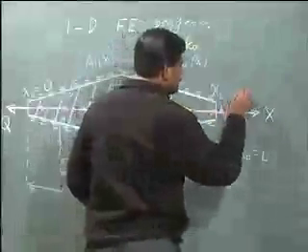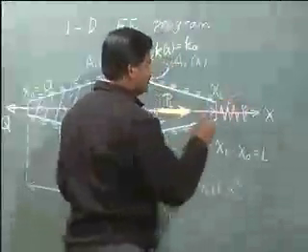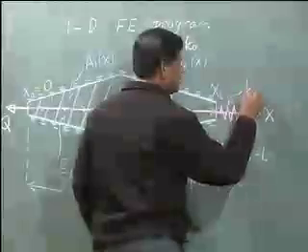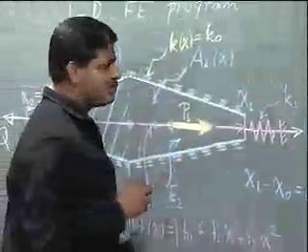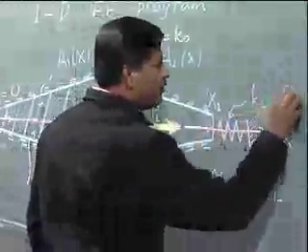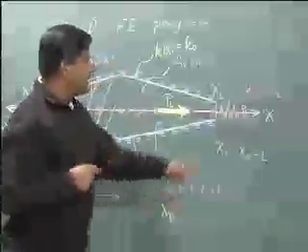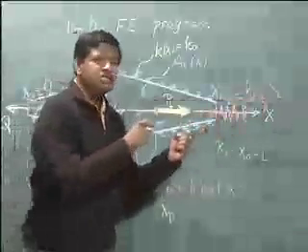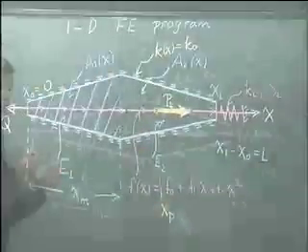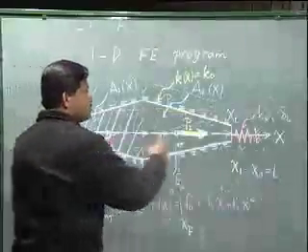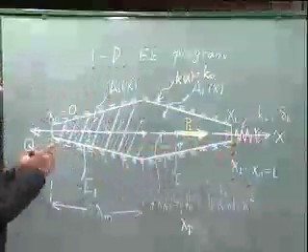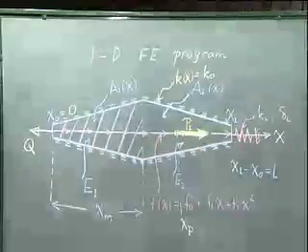If it is a force applied by an end spring, for the spring I have to specify the stiffness coefficient and whether it is pre-compressed or not. Delta L is the initial compression of the spring. This spring could be applied here, this force could be applied here, we could have any mix and match of these various kinds of boundary conditions.